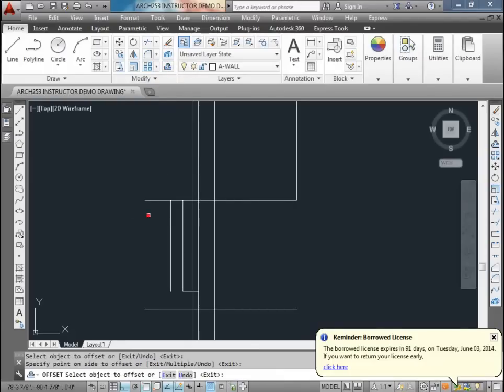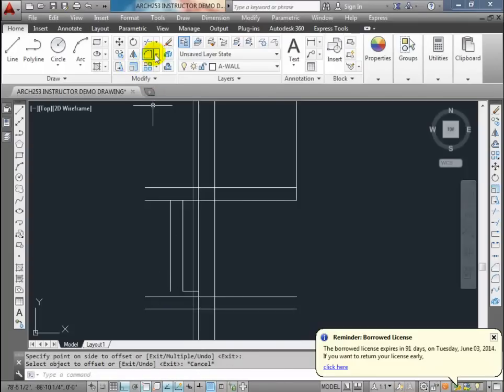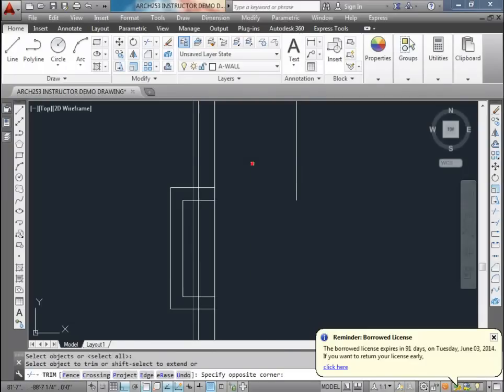So I'm going to offset 4.5 inches this way. And because this is the bottom side of this wall, I'm offsetting 4.5 inches this way and 4.5 inches this way. And now I'm just going to clean up all of my corners. When I use the chamfer command, I'll clean up this wall to this wall to this one, this to this, that to that, and I'll just delete out all the excess. Again, I'll use my trim command here.